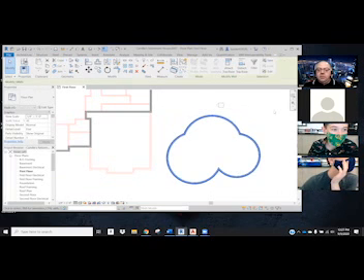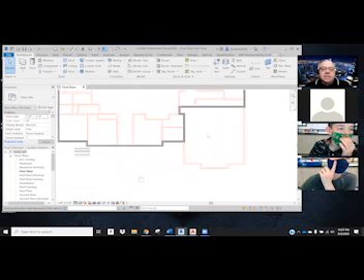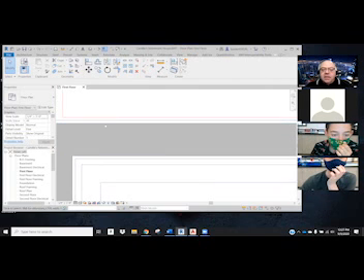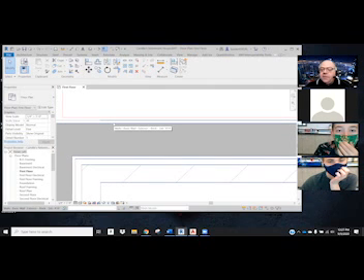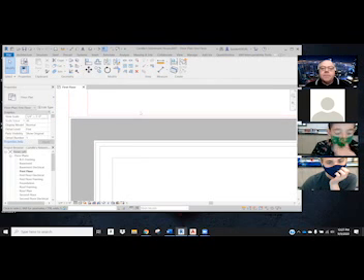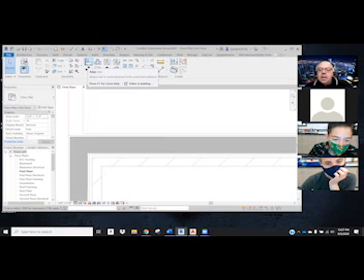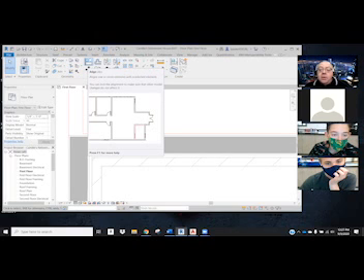Okay, let's go here. All right, now, as I said, I've got this error. I'm in the Modify tab right now, and I need to line this wall up. It's a very little piece that I'm off. To do a screenshot, it's print screen. When I'm in here, I have a tool called Align. Align is what we use to fix even rounded walls. We'll make them match up with the wall you have below. So Sam, just get it close, and then we can use this tool to fix it.